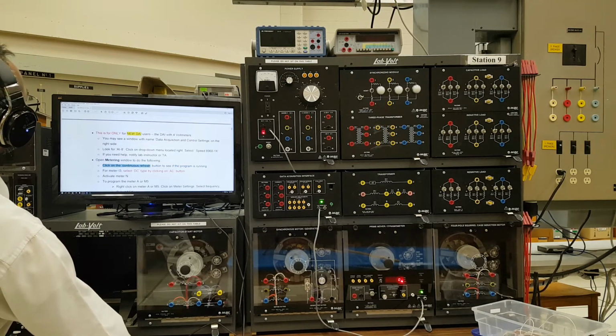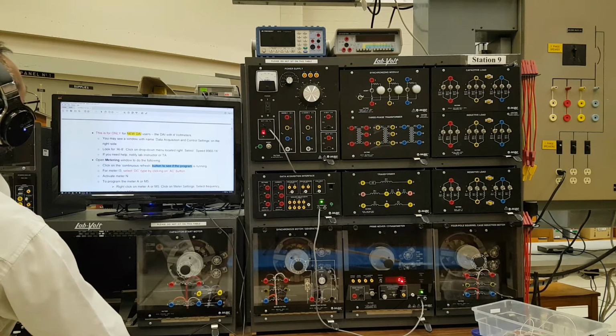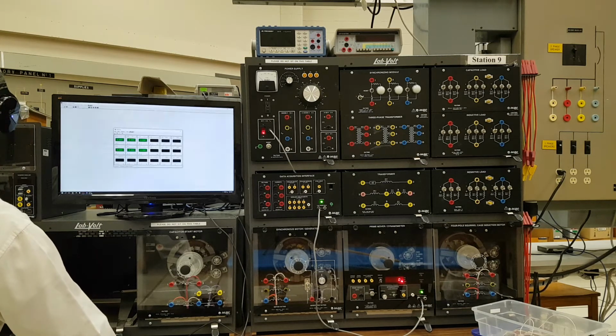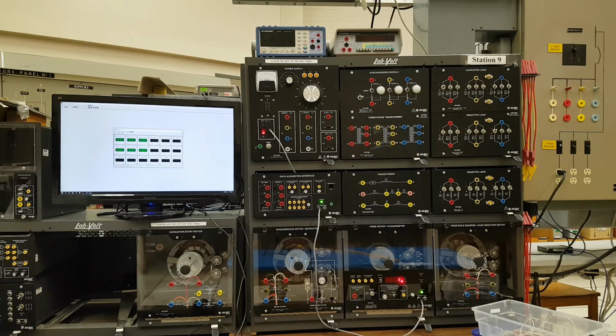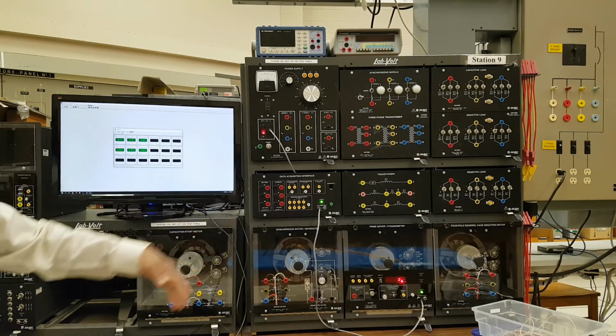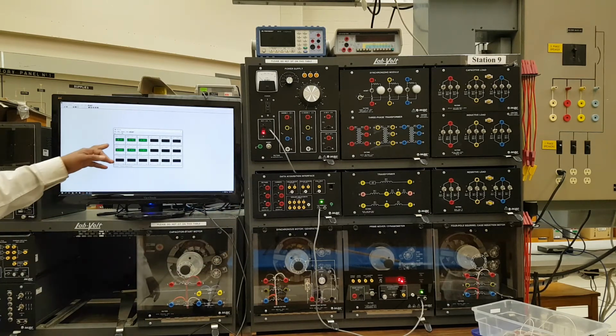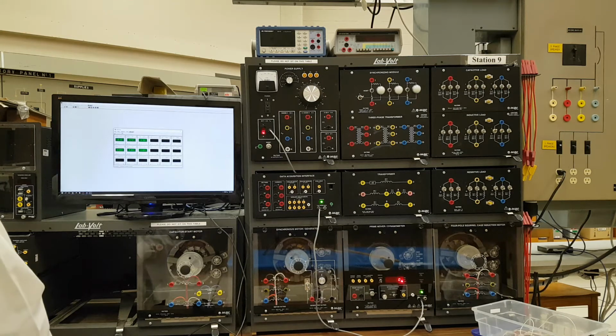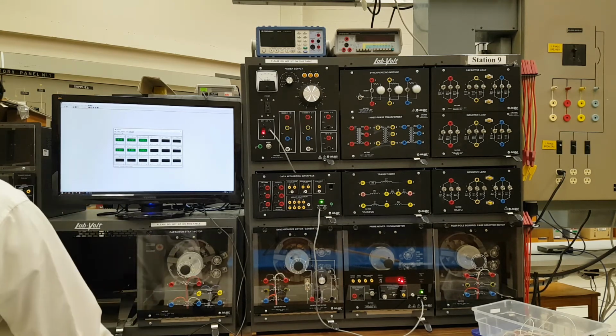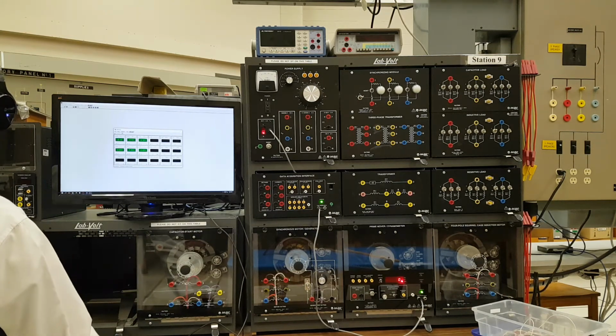Click on the continuous refresh button to see if the program is running or not. So I usually click this one to see whether these values are varying or not. Sometimes if it is not correctly working, you would see 120 volts without applying any volt. That means it's faulty. So that's why we do this checking.